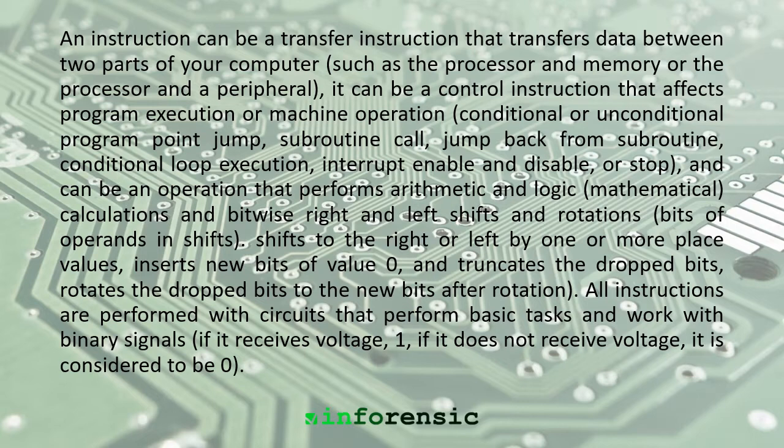It can be a control instruction that affects program execution or machine operation: conditional or unconditional program point jump, subroutine call, jump back from subroutine, conditional loop execution, interrupt enable and disable, or stop. It can also be an operation that performs arithmetic and logic: mathematical calculations and bitwise right and left shifts and rotations. Shifts move the bits of operands to the right or left by one or more place values, insert new bits of value 0, and truncate the dropped bits; rotations move the dropped bits into the new bits.